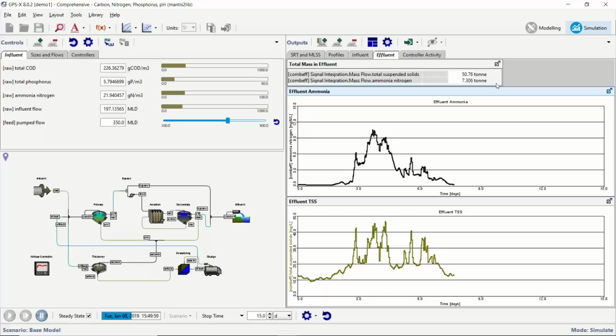When you do that process, I forgot to mention when I was on the slide, you will find that it comes out in our default mass units, which are grams. So one thing I always highly suggest is go through that process I showed you earlier, and when you get to the end, switch from grams to tons or something else, because it's going to be a big number. You don't want to have to plot 11 billion grams. So flip it over to tons.